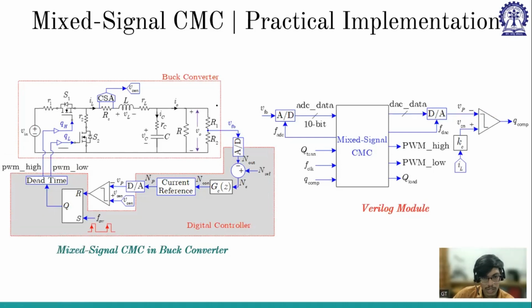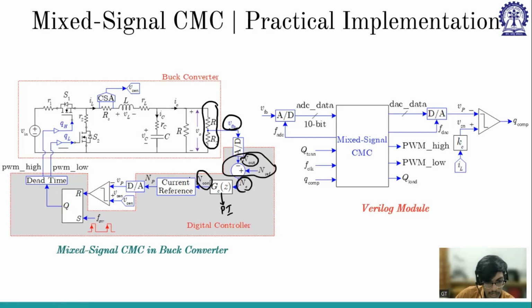So the voltage is stepped down, and then we get V feedback, which is going into the analog digital converter, gives us the digital equivalent number subtracted from the reference, giving us error. Now it passes to the PI controller, gives the control voltage. Then we had discussed the design, the importance of the current reference in terms of keeping saturation and converting 2's complement to offset binary, and the Q format matching. All these manipulations will be done in current reference, and also protection purpose, like peak current saturation as well as valley current saturation we can incorporate in the code we had discussed.